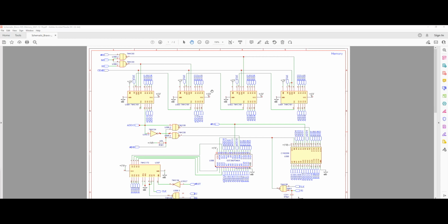So let's say you have a program that has 5 steps. You run up to step 3, and in step 3 you want to jump to a different memory address and do something there, let's say save a value, and then come back to the same step in our program counter. That is achievable by having a dedicated memory address register here, which by itself is a counter, and it can count and move into different memory addresses and come back to the same address if needed.